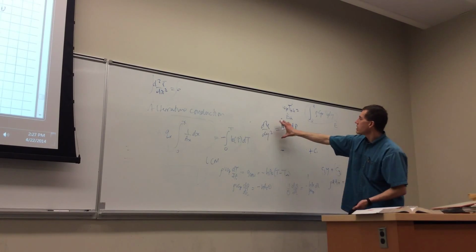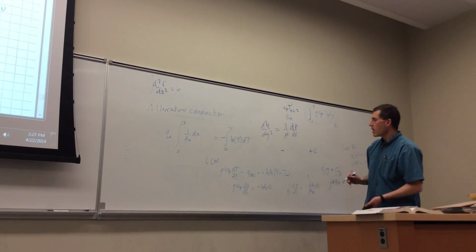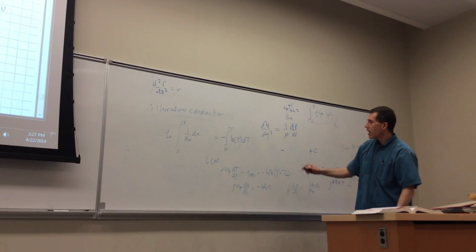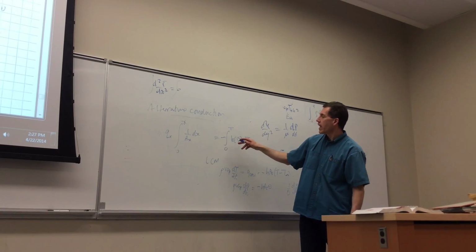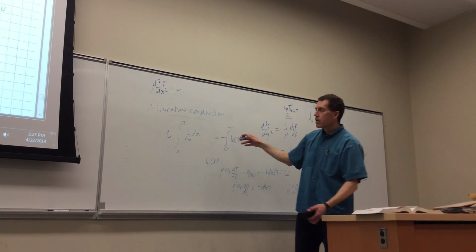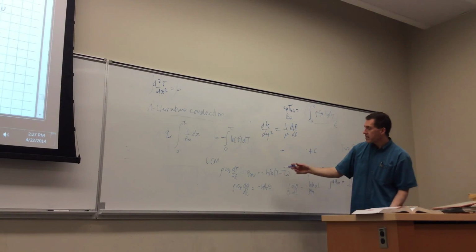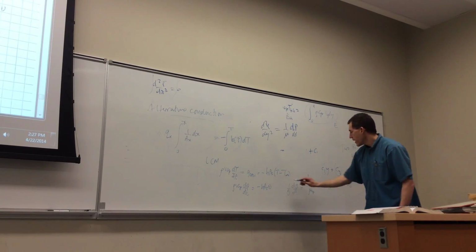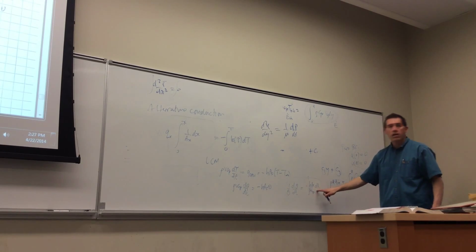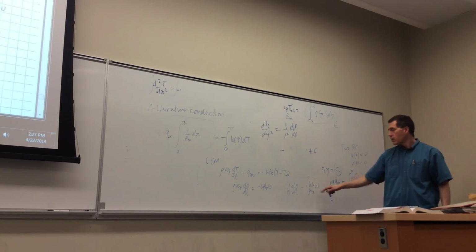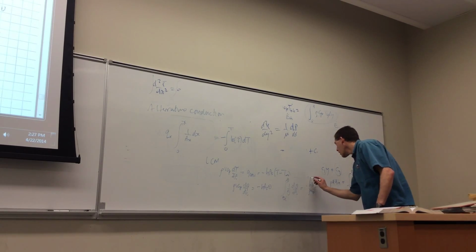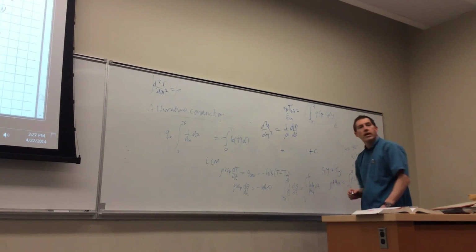So we did solutions where you integrate twice and solve for coefficients, or we did analyses where you had separated into the two sides, and put in a function for k if k was a function of temperature, or we put in a function of area. We ended up with something like this, and when you integrate that, you get the natural log on the one side and a constant times temperature on the other side. So you can integrate this one from theta i to theta and 0 to t, right?